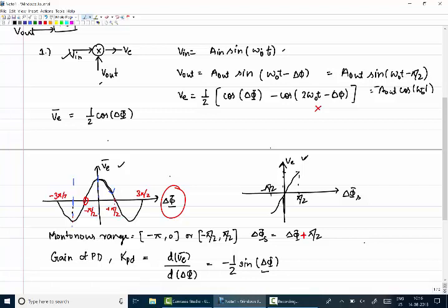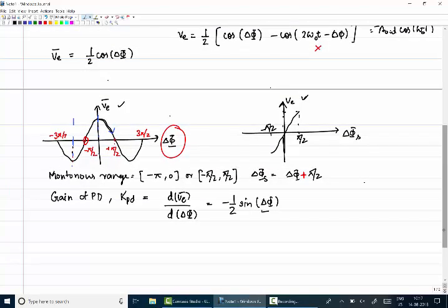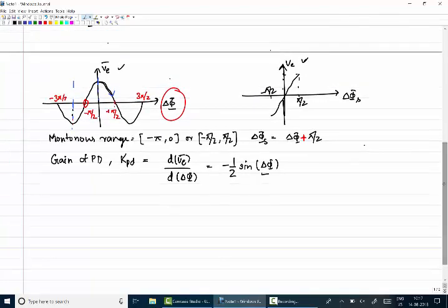If the input frequencies are the same, now for a type 1 and order 1 PLL or type 1 and order 2 PLL, do you agree with this part? Now if we take, let's say, a type 2 PLL also, if the frequencies are the same, the control voltage which is required is 0. Now what should the phase error be?